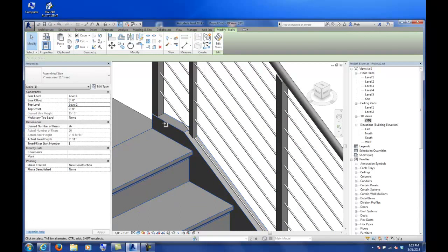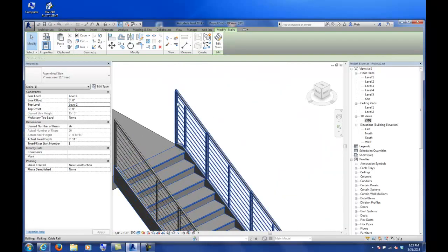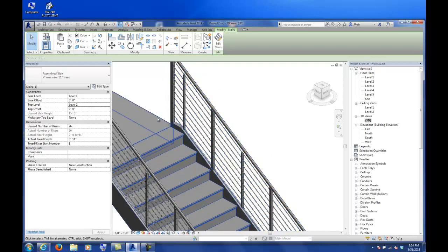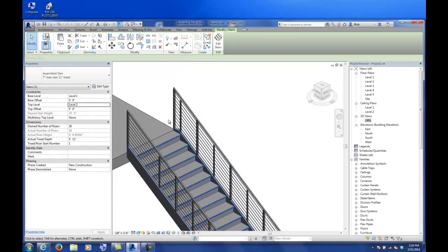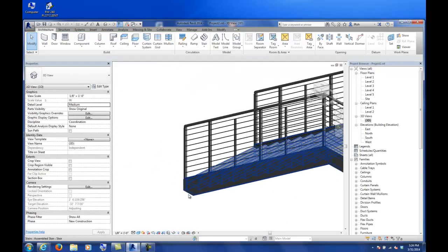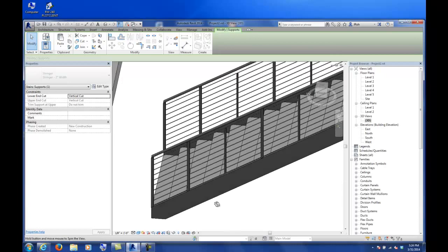We can also click on, and we'll talk about this railing here in a minute because it's actually incorrect in the fact that since I have this stair tread flat at this level, all of this part should be flattening out, to actually be only 32 inches above at this particular level. So I'll go over how to fix that in a minute. But again, if we tab over and select these stringers, this is where we can select our trim, do match landing support. And down at the bottom, we can do the same thing.